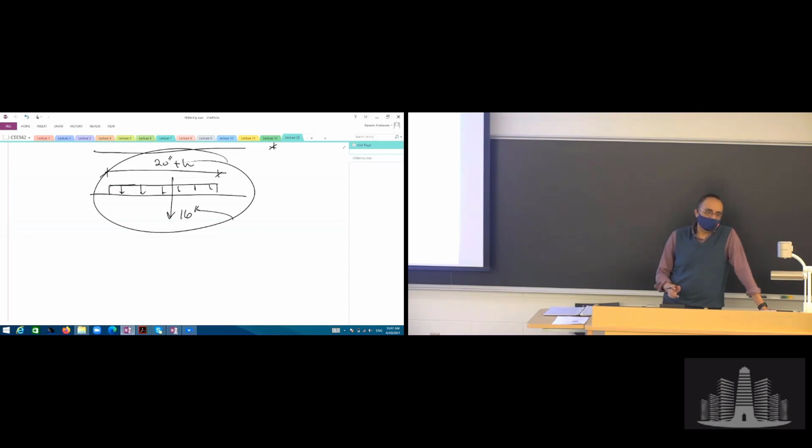This is the traffic. Remember at the beginning when we said the design lane width is 10. But when you talk to the transportation engineers, they consider it as 12. So, in other words, it doesn't matter whether it's 10 or 12, because that will change depending on the width of the bridge. Remember, it could go as low as 8.5 or 9 feet. What is important from this, and that's why it's placed in AASHTO, is that you have to keep clearance between both trucks, assuming that each one occupies a lane, whether this is a 10 or 12-foot lane. So typically it should not be less than 2 feet from the edge of that lane.